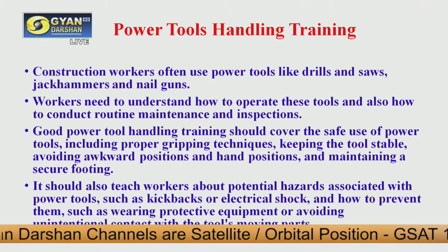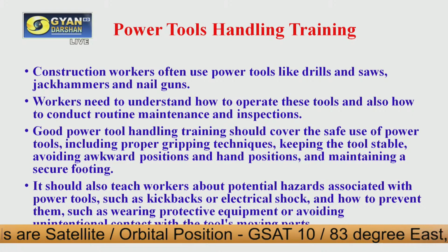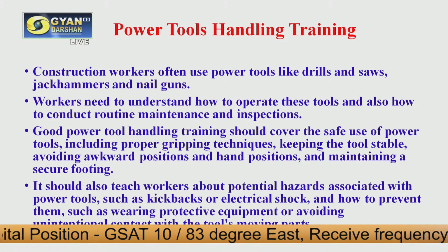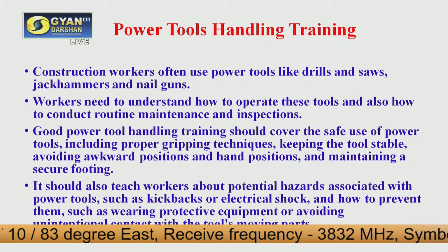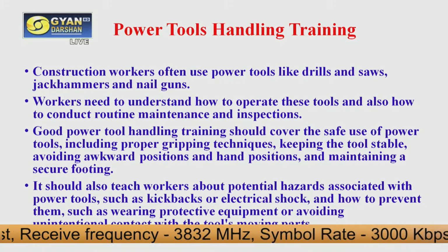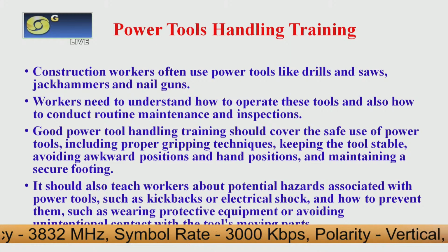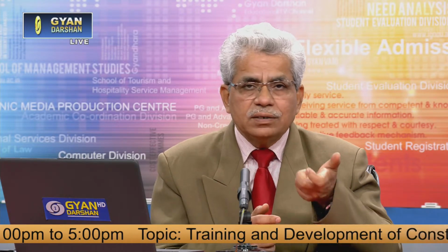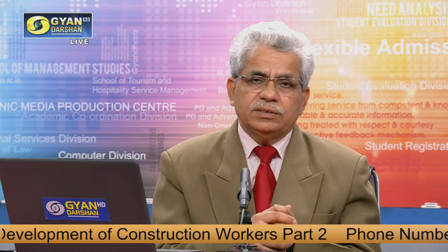Then good power tool handling training should cover the safe use of power tools, first of all including proper gripping techniques. This is also very important. When you are using these power tools, one should know the proper gripping. If you are handling these tools carelessly or with a casual approach, because these tools run on electricity and have a lot of power, you cannot just hold them loosely. Otherwise, it may kick back and cause injury.